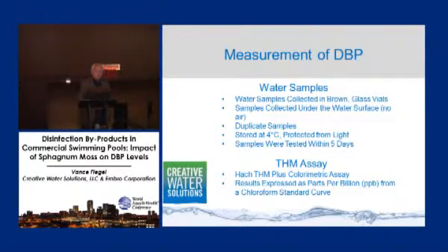Measurement of disinfection byproducts. We use an off-the-shelf method from Hach. I'll talk about that in a minute. The water samples were collected in brown glass vials. These are certified vials, certified to be clean and non-contaminated. Samples were collected under the water surface and capped under the water surface so that no air was trapped in the vial during sample collection.